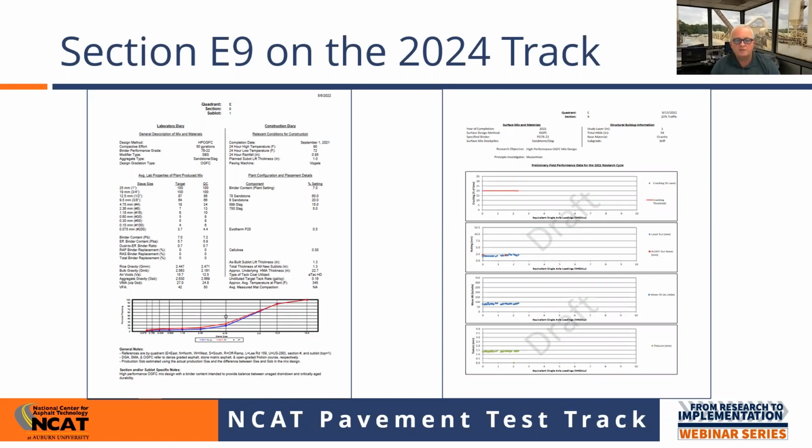So this had a lot of asphalt in it, and what we ran had certainly 3/4 to 1% more liquid in it than what the oil-based design procedure would show for this mix. But it was a 4-bin mix, and that's another important thing to point out about this mix.